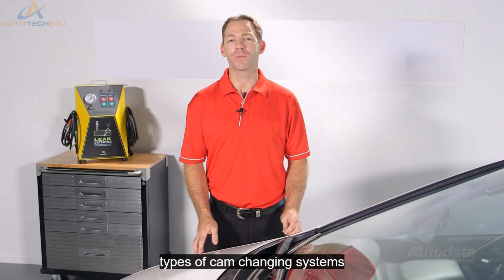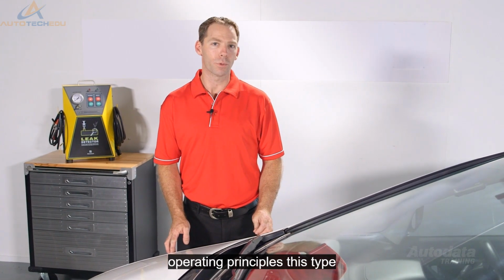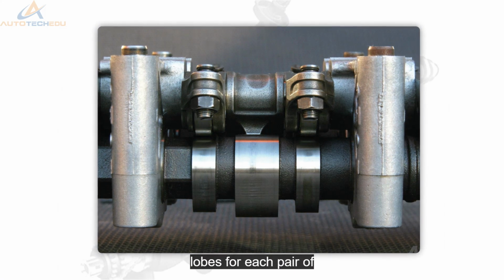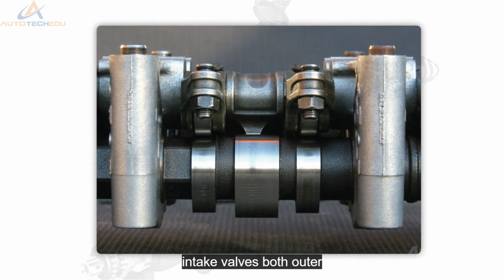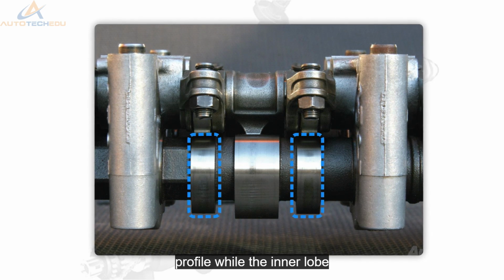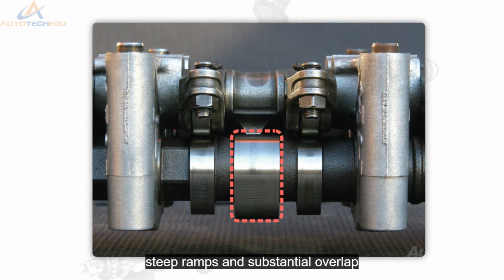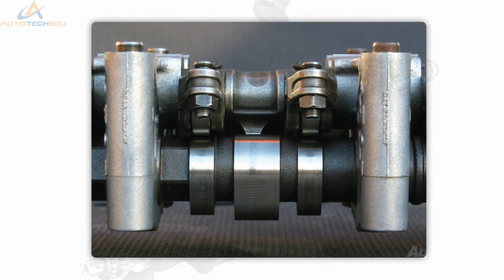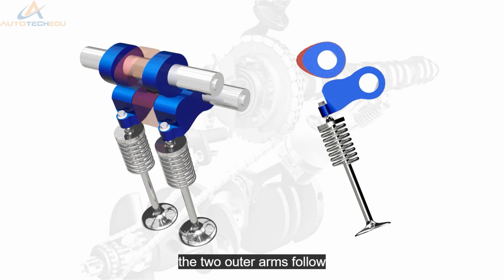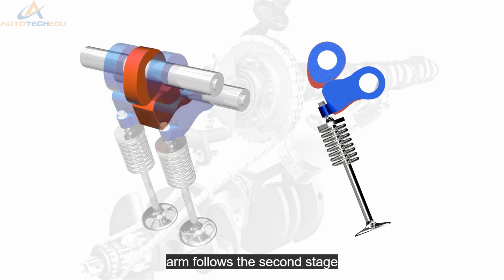Although there are many types of cam changing systems in use, they all follow the same operating principles. This type of system uses 3 cam lobes for each pair of intake valves. Both outer lobes have the same mild profile, while the inner lobe is ground with an aggressive lift, steep ramps and substantial overlap. In this system, there are 3 rocker arms. The 2 outer arms follow the first stage cam profile, whilst the inner arm follows the second stage profile.